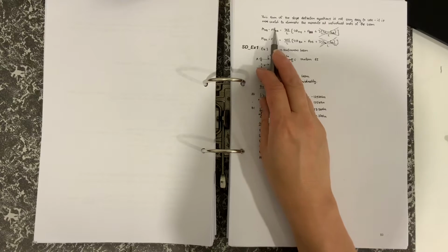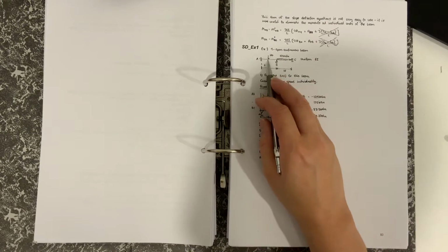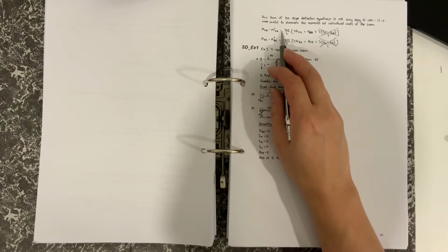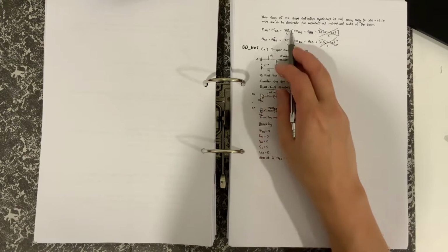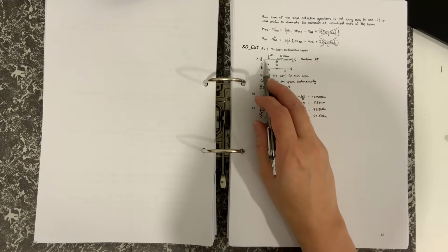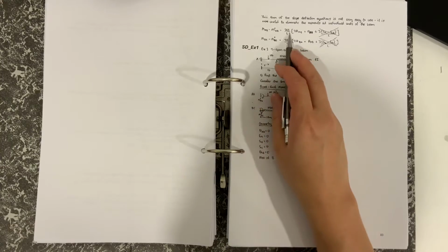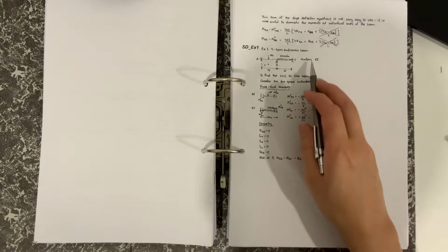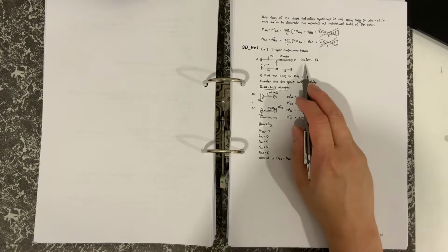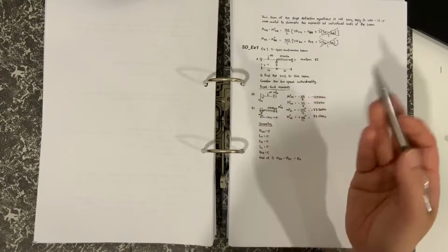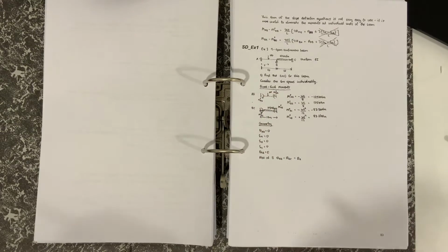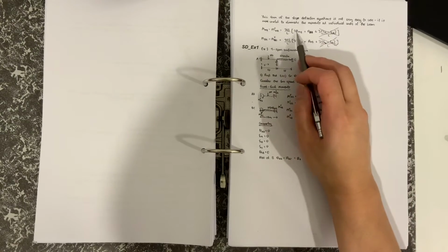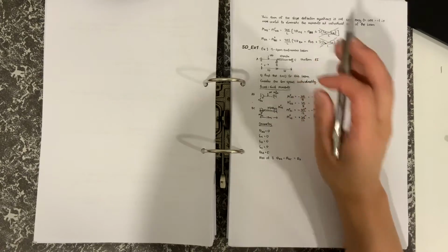The fixed end moments we'll be calculating, as you've seen, and it's going to be equal to 2 times EI, where EI is the bending stiffness of the beam, divided by L. Sometimes in the examples, one beam would have twice the bending stiffness of the other beam, but in most cases you would say uniform EI, i.e. that span and that span are both from the same steel and the same cross section. Then we have 2 theta AB.